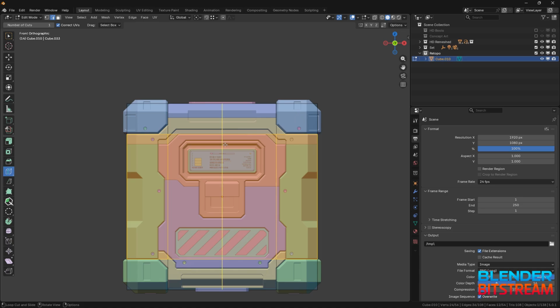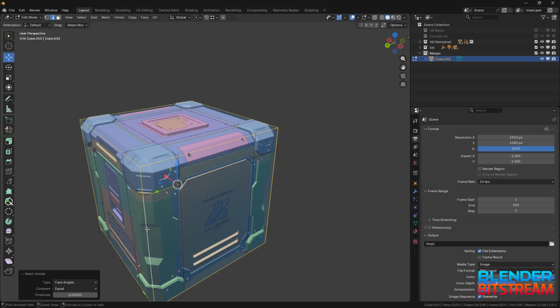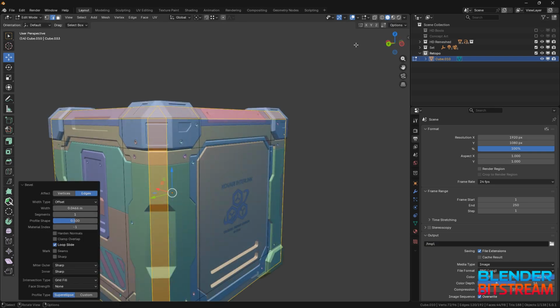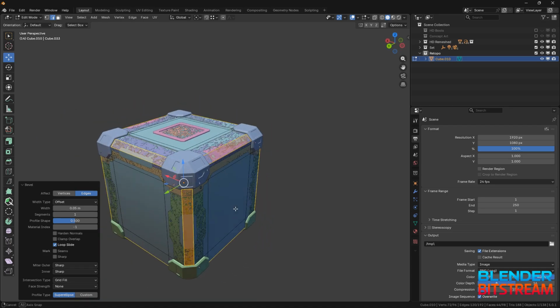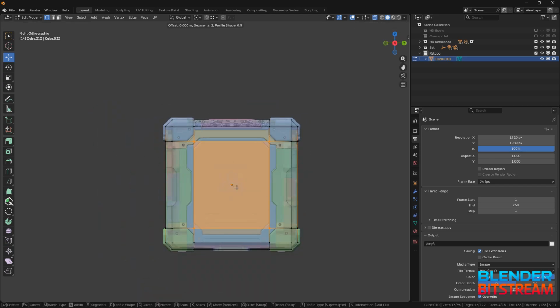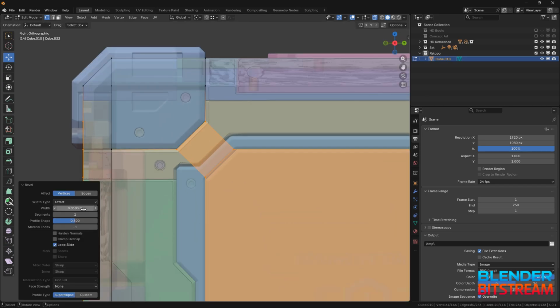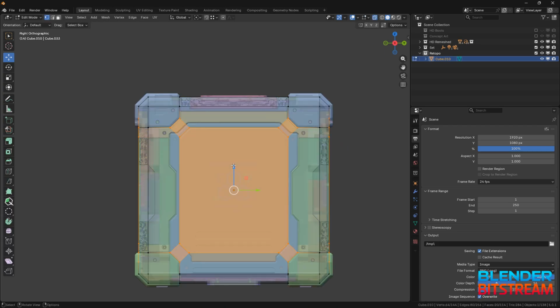Our main goal here is to get the same silhouette detail as the high poly mesh, but with greatly reduced poly count. Convex corners are especially important in making an object's silhouette appear to be detailed. Beveling some convex corners can go a long way, and help the object look just right from every angle. Concave internal corners with a smaller curve can be handled by the normal map and don't need to be beveled.